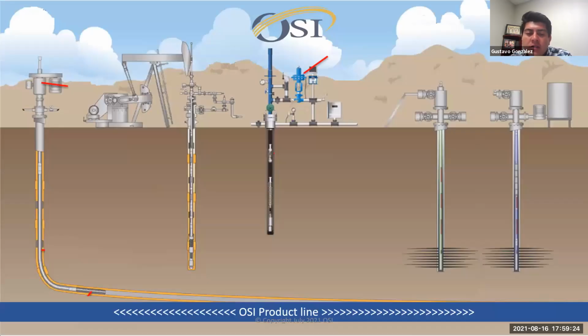One of the main focuses they asked us to talk about is sand control, or sand management, for all the different artificial lift systems. There is a different approach to sand control whether it is PCP, rod pump, or ESP. Based on the application, whether we're dealing with a conventional or unconventional well, we may decide on different ways to deal with the sand.